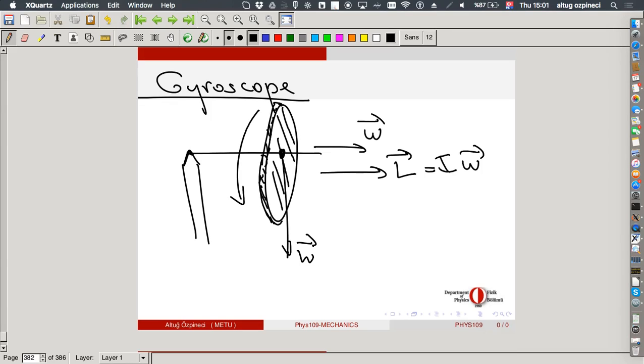And we had already said that the acceleration of the center of mass is only due to external forces. So if the force acting at this rod at this point was vertical, what creates this central acceleration of the center of mass? The lesson of the story: the force exerted over here is not vertical. At this instant, it is somewhere in this direction.